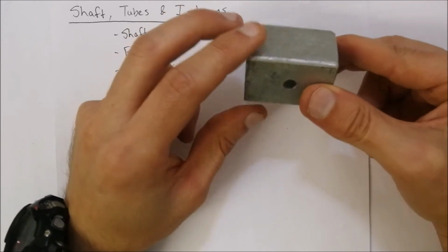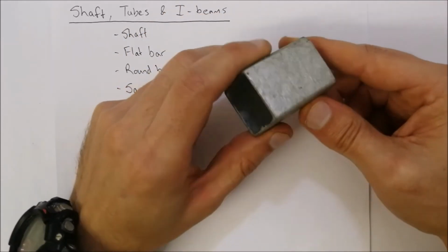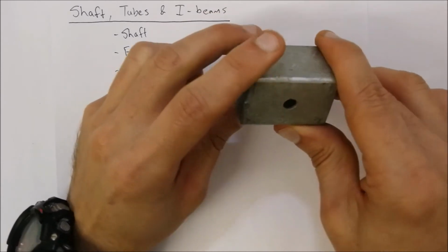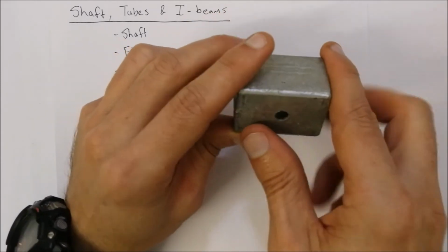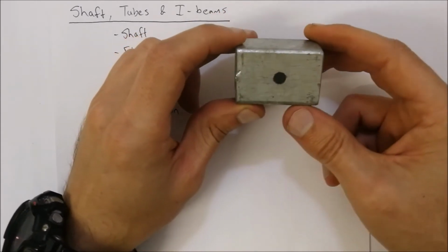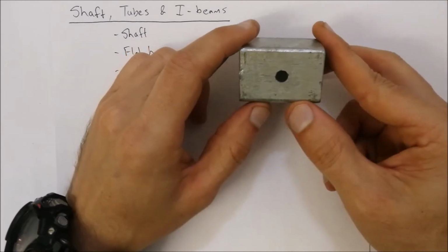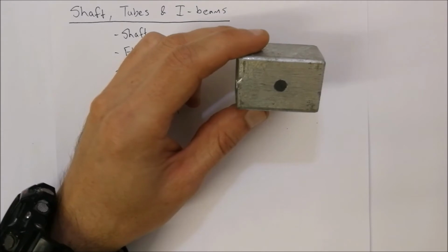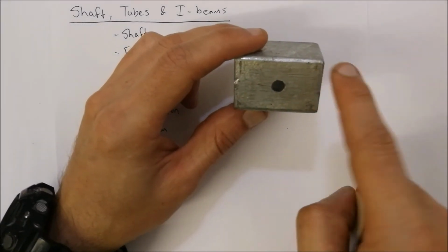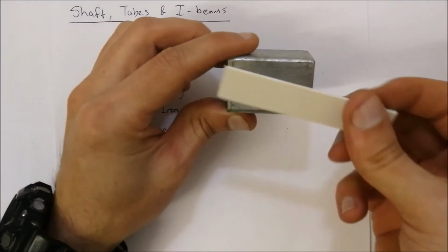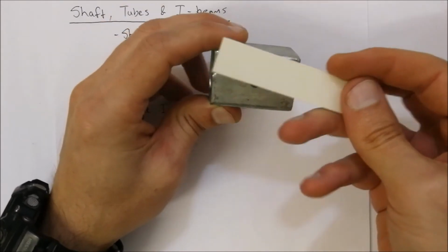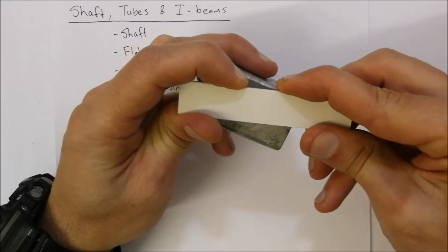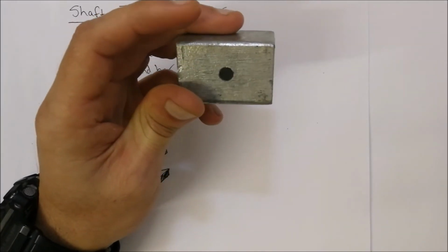Square tubing, but again, we've got a situation that we've got now a flat surface over there, so that on the top there's going to be compression. At the bottom there's going to be tensile forces. But then again, if you look at this piece over here, and you look at the piece behind it, it's a flat bar. And we know that with flat bars, it's not easy to bend it in that type of orientation.